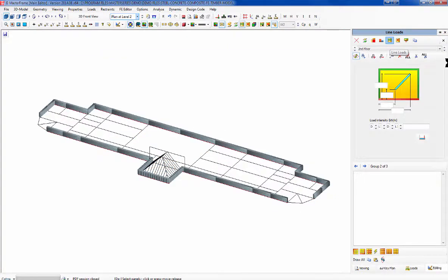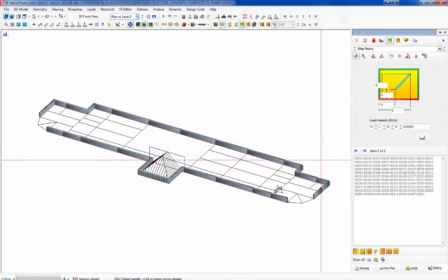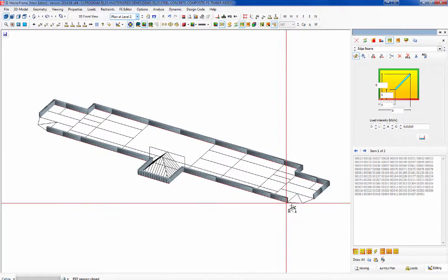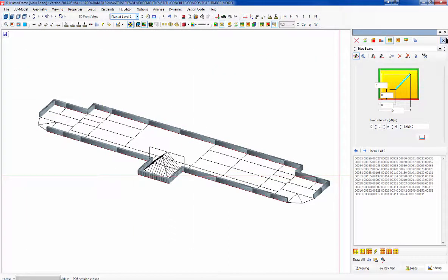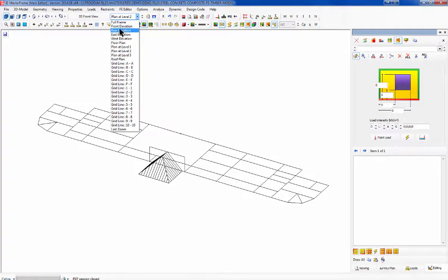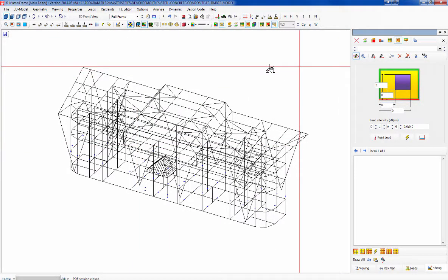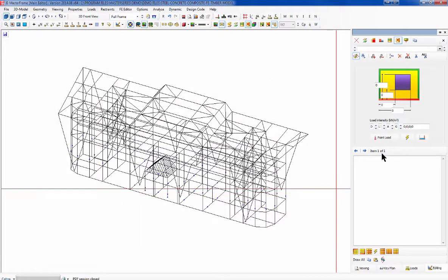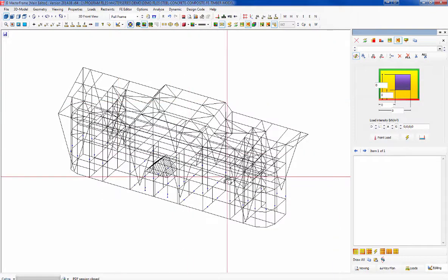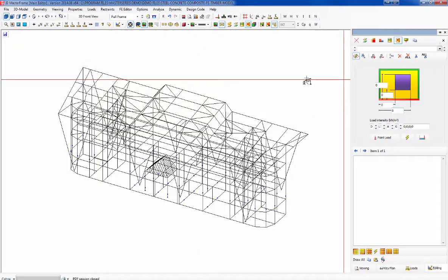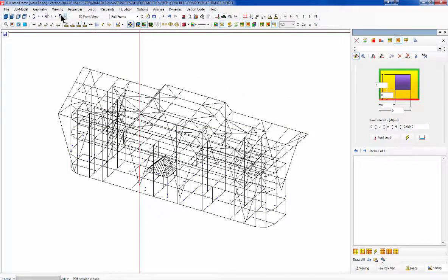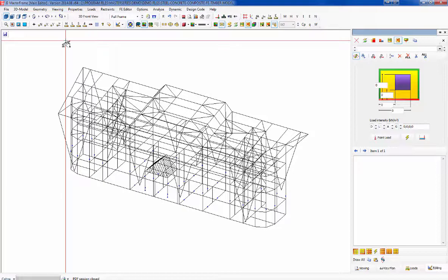We can look at wall loads. He's got glazing around here, so he's not putting any glazing in these lovely corners, but everywhere else he's got these lovely wall loads. Has he any patch loads? Well, maybe not here, but let's see the full frame. He has no patches on the structure at this moment in time. I'm not going to put one on, I just want to save time, but we can put patches on the structure if we want. So that's our area loading on our different levels.